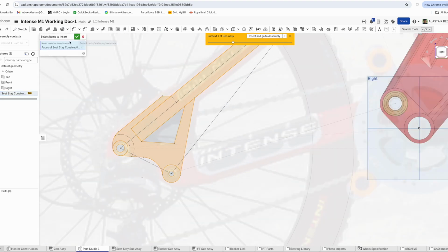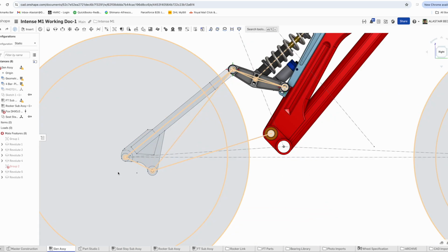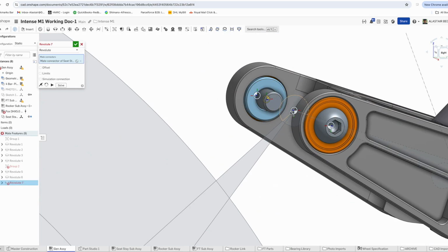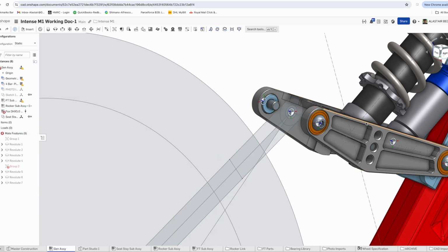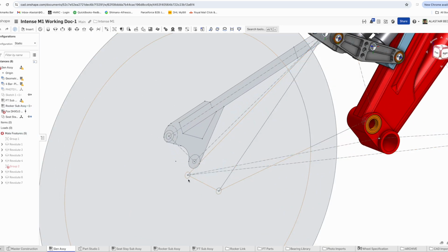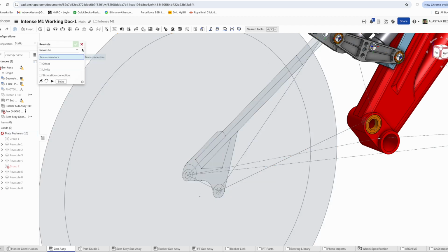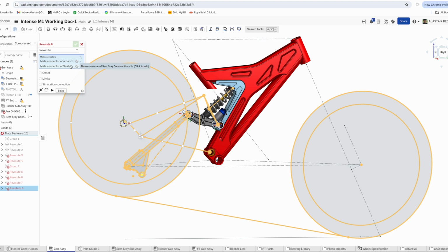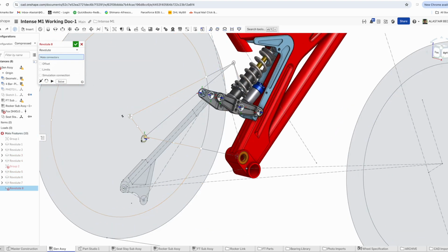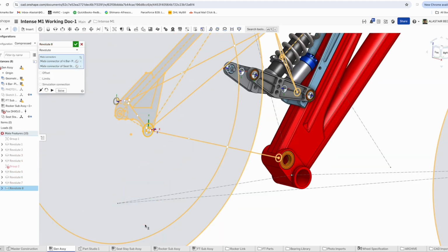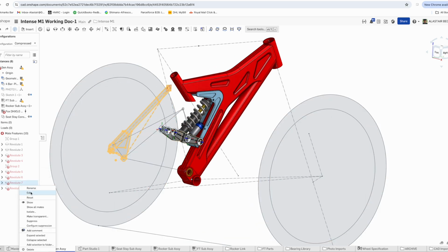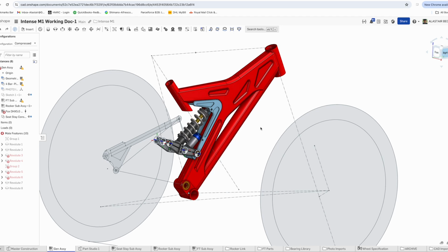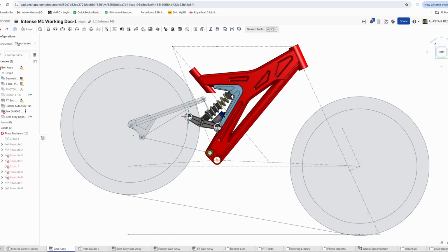So this is the part where we bring that sketch that we've just created into the main assembly and fix it, or well, actually we're going to mate it in place with these center mates. It's a good way of checking that clearances and everything works and functions with the sketch before you start modeling. So there you see that actually one of the mates must have been incorrect, so that sketch that we just inserted should have moved with the rest of the suspension. It's the equivalent of using blocks in SolidWorks. Onshape doesn't call it that, but it's the same thing.